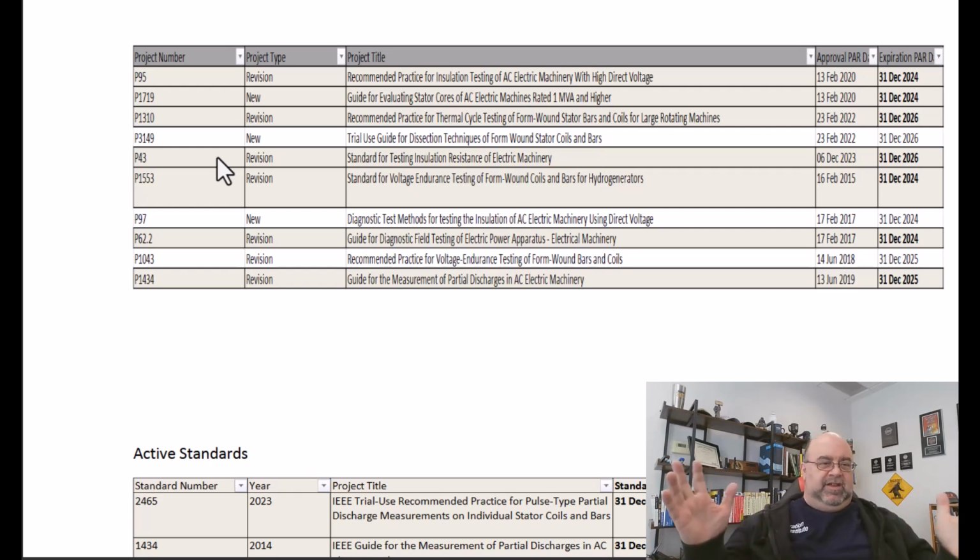Those who look at it and say the Arrhenius equation, 10 degrees centigrade means double or half the insulation resistance value, have not seen anything since the IEEE Standard 43 1974. So it's changed a lot over time. We're working on it again.